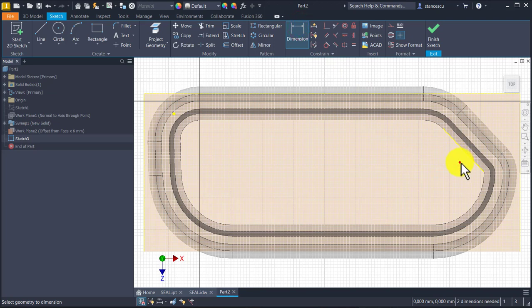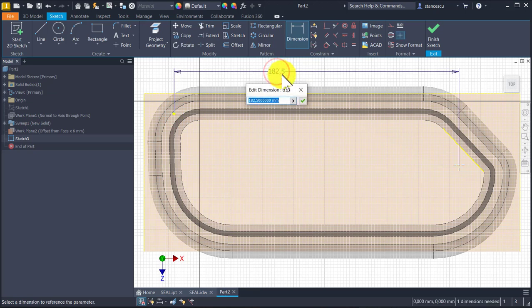this dimension horizontal from the center point is the value in the drawing, 171.4 plus 16.5, the radius of this second arc, with a radius of 16.5. Okay, and the distance on vertical is 19.7. From where? From this line, from the center point.